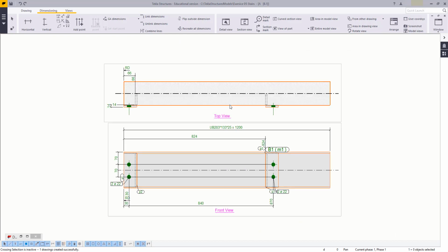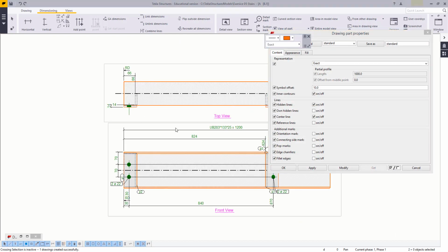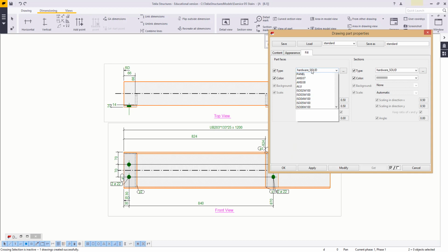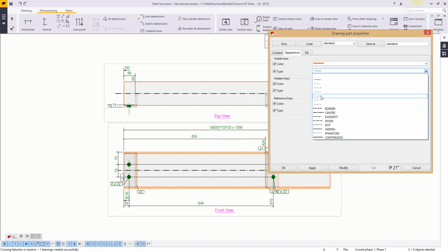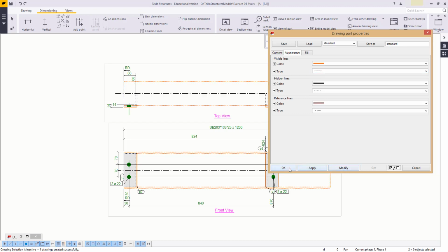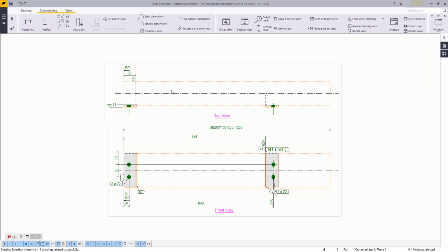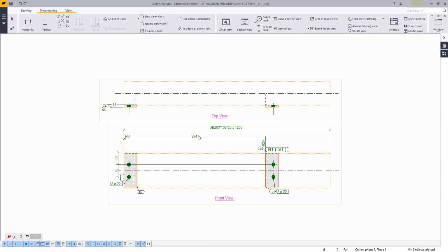Upon opening this up, you'll see that everything is this nice grey color that we had to put into our GA, but we don't want this specific item to be that, so we're going to check that off. Next, we don't want any dimensions referencing from a specific point, nor do we want the beam's actual size or part mark.